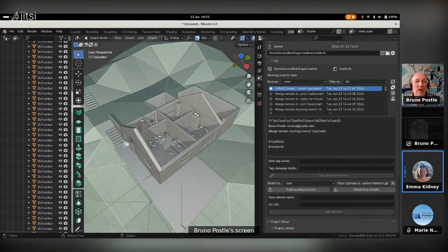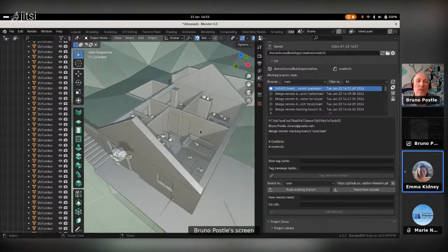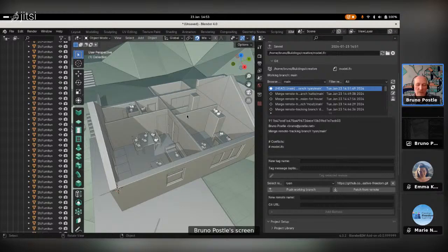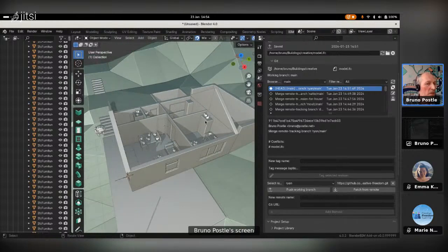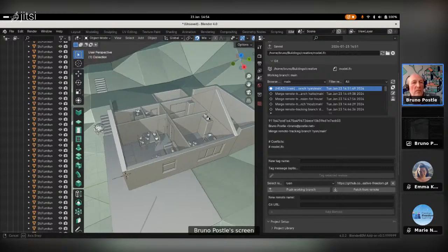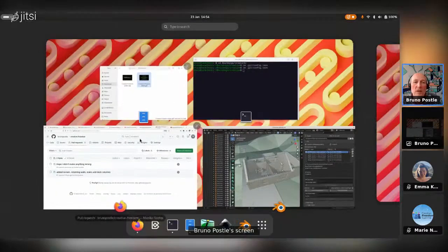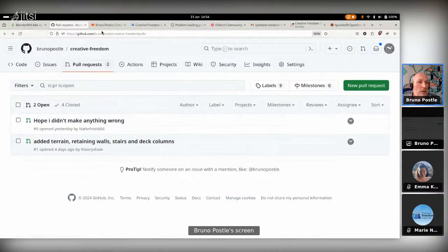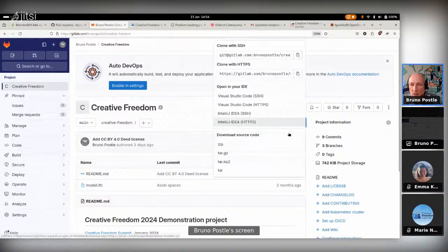Yeah. There's just another one there. Does it account for floor and height differences? Yes. IFC has a very elaborate system of locations, so you can georeference everything. You can model multiple floor buildings. And when you generate drawings, it will generate drawings per floor. It will identify the number of stories already in the file. So when you generate drawings of each floor, the software already knows where the floors are.